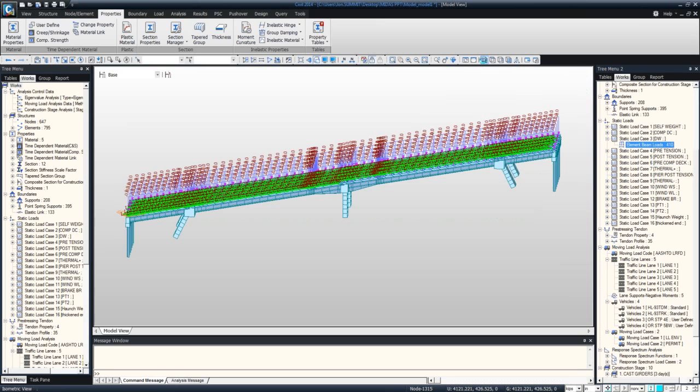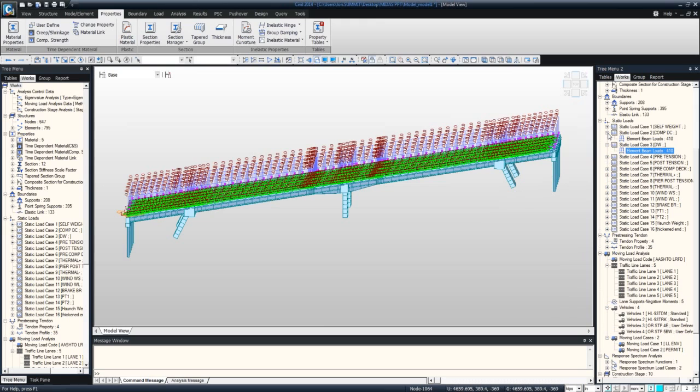The other loads in the model are some superimposed dead loads for the barrier rail, the wearing surface, the standard loads. Also a superimposed load for the haunch. Based on the post-tensioning cambers, we'll have anywhere from a 1-inch to a 3-inch haunch above the girders to allow for a level deck.